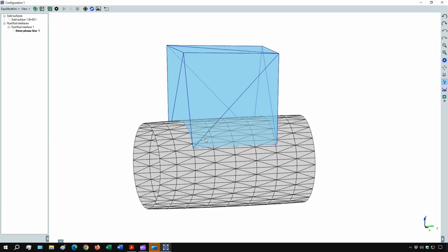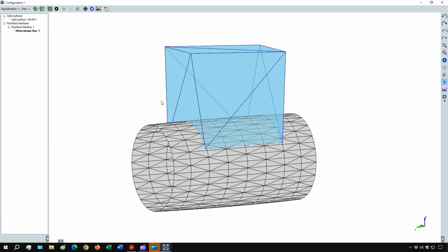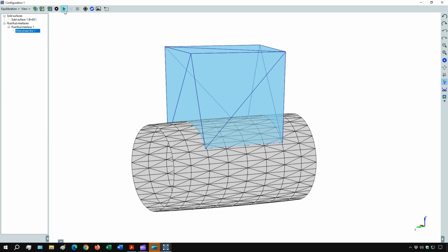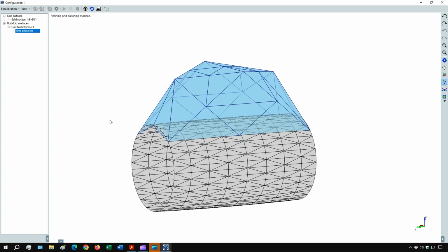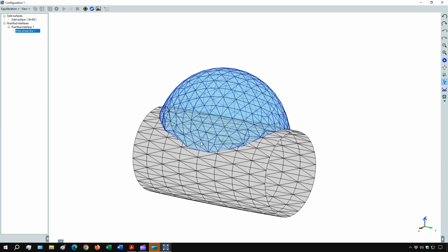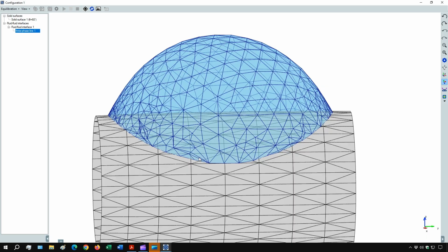All mesh edges going from a boundary vertex to an internal vertex should now be attached to the external side of the cylinder. So, we should now be able to select the solid surface mesh as constraint for the fluid interface boundary. And indeed, this time it worked. We can now launch the equilibration to calculate the equilibrium shape of the droplet wetting the cylinder for the selected Young's contact angle.